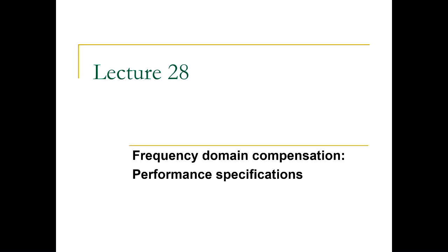All right, good morning. So as I said yesterday, we will skip one lecture, which I will come back to at the very end. So we will push on with the frequency domain compensation. So today I will talk about performance specifications. So the first step when you are doing controller design via Bode diagrams is to translate your performance specifications into the desired shape of the compensated open loop transfer function Bode diagrams.